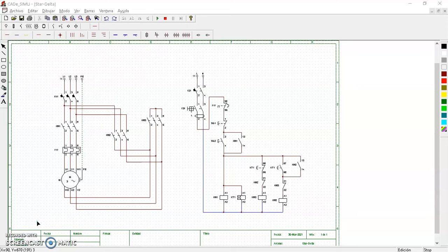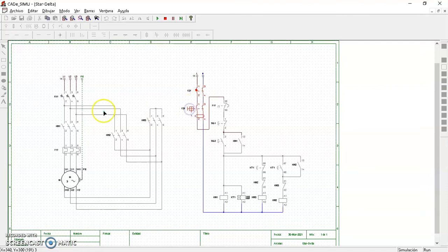In this scheme, two auxiliary contactors in addition to the main motor contactor are required. One for the star start with common point and one for delta start. When the start is initiated, a timer is activated. When the time expires, the delta start is switched, thus achieving a lower starting consumption. These contactors are incorporated in the coil branch, on the opposite branch, to avoid activating both contacts at the same time and causing a system failure.